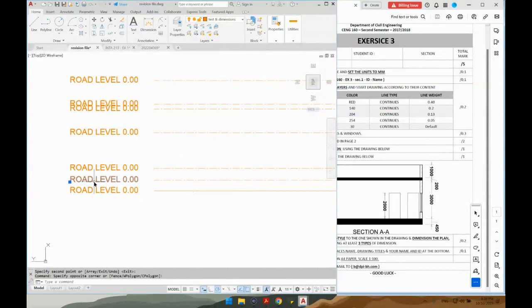And start changing the type. So this one is ground level. And it's plus 450 above the ground, 450. Then for this one, this is the cell height, which is plus 950. You need to add them. Cell height is the window from down. Then I have the lintel height, which is plus 2000 plus 450, which means 2450.